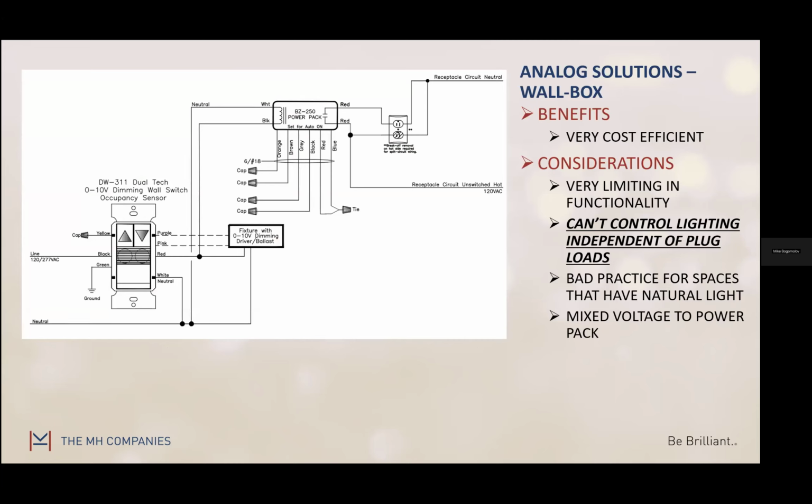So there are right ways and wrong ways to do plug load controls. And what I've seen, because they do drive the cost of the projects, control specifically, a lot of times it's the first thing that people try to VE or find a way to do more cost efficiently. So here's an example of a private office application where typically you would have a wall box sensor that's line voltage, dimming capable. Technically, that checks all the boxes in the code required for that space in terms of controlling your lighting.